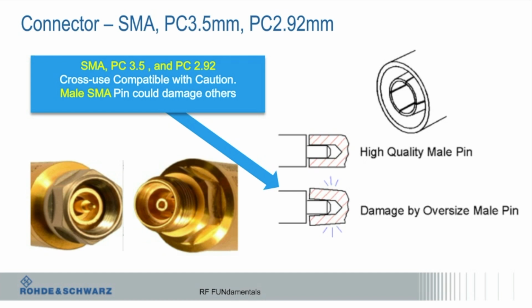But that thing should be pretty much tight right together. Those spaces should be minimal on all 4 of those spaces. And if you see, like, sometimes one of these might be bent back a little bit or the spacing is different, that's when you go, yeah, maybe this connector's damaged.